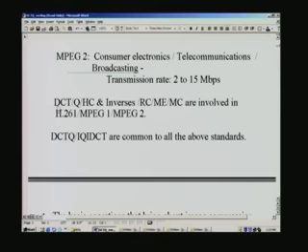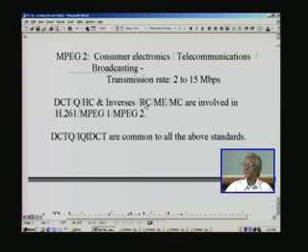So here what is said is DCT, quantization, Huffman coding and their inverses, as well as what is called rate control. Rate control is part of the VLC or VLD, in the sense that depending upon the picture you may be compressing, we can't predict how much will be the utility as far as the transmission channel is concerned. It may not be utilized for a brief while. So if you look at the bit stream coming out, it will not be uniform. In order to make it constant and uniform, you need to place what is called rate control, which is part of this VLC, and we are not going to discuss VLC.